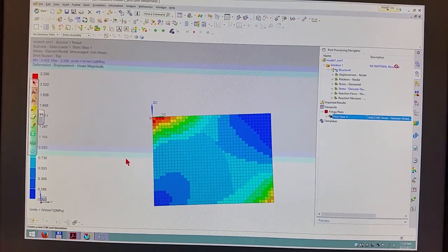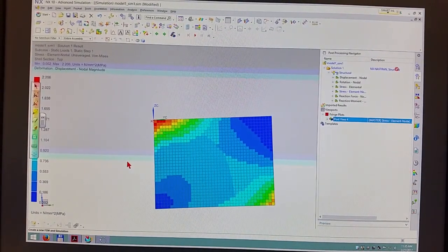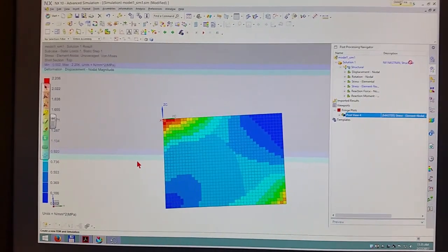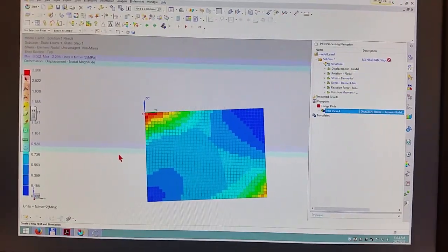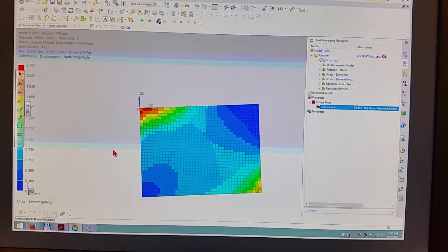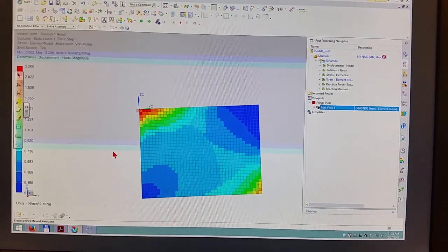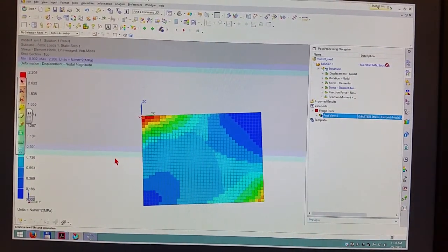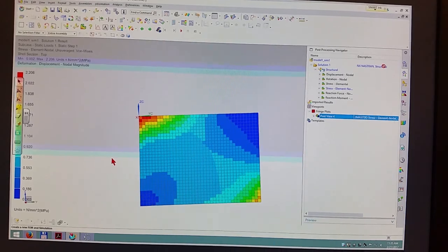I know this is going to happen. So one, I can put a fillet there. Or two, I can minimize it. One of the ways we minimize it is we make my mesh fine right there, right? So I come in and I put a brace there, at that intersection.